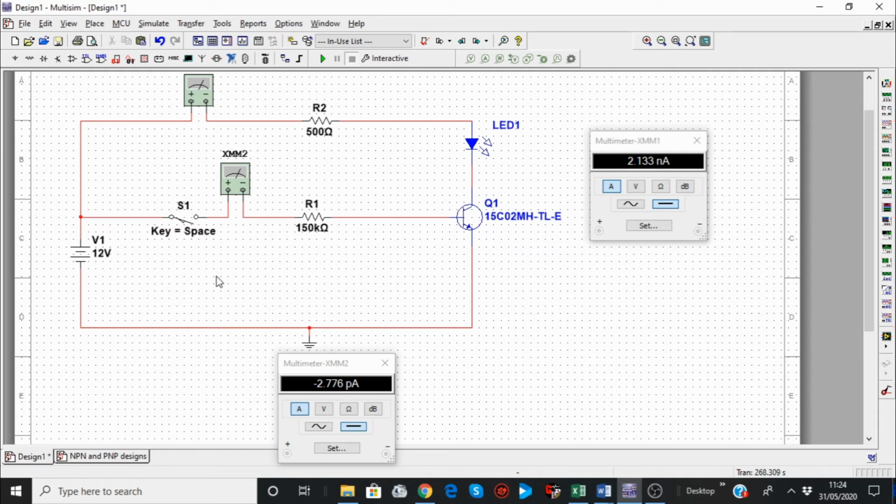You can ignore them. So a much bigger resistor here, to reduce the voltage, that 12 volts, to a really low voltage. We only need the voltage between base and emitter to be about 0.6 to 0.8 volts for this transistor to switch on. For any transistor to switch on, that is the range, 0.6 to 0.8 volts, depending on the types of the transistors. Whereas for the collector, we only use 500 ohms because this LED is capable of tolerating 12 volts, and so we're only limiting the current a little bit so you won't burn it out. Emitter is directly connected to the ground and negative part of the battery.